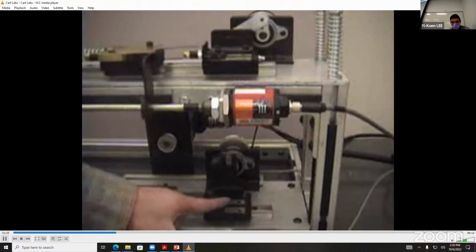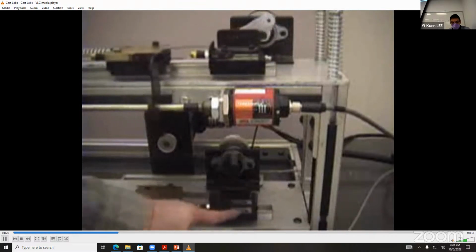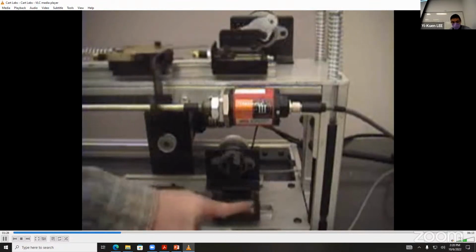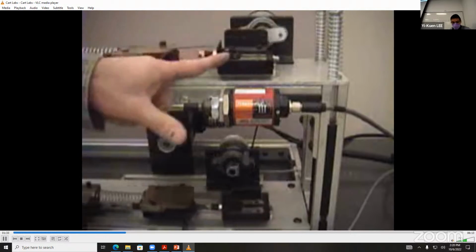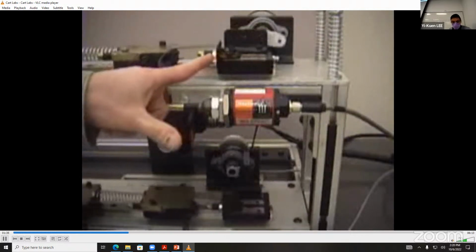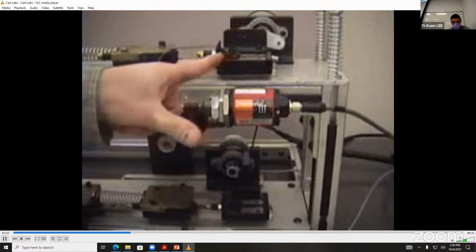Again, the Scotch yoke has pure sinusoidal motion, and you can see that in how smooth this output cart is moving. But you'll note that with the slider crank, because it has an extra frequency component, the motion is not as symmetrical, and it appears to return a little bit quicker and have a little bit of pause in the motion. So here we're plotting the output from both the slider crank and the Scotch yoke mechanism.